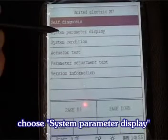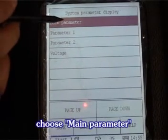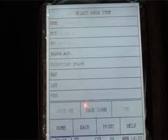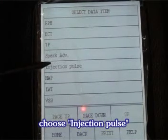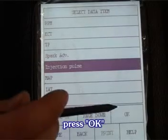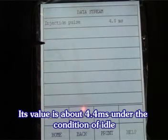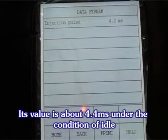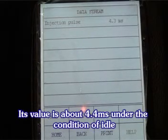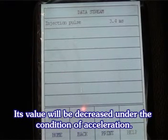Choose System Parameter Display. Choose Main Parameter. Choose Injection Pulse. Press OK. Its value is about 4.4 milliseconds under the condition of idle. Its value will decrease under the condition of acceleration.